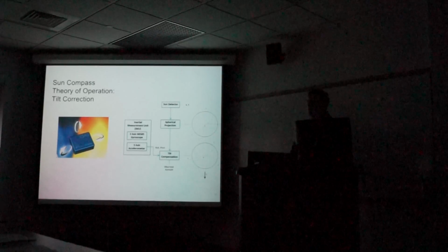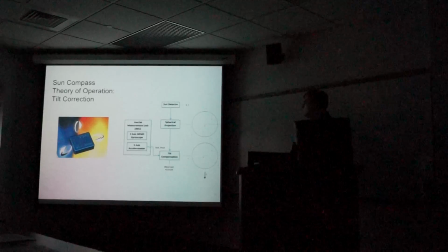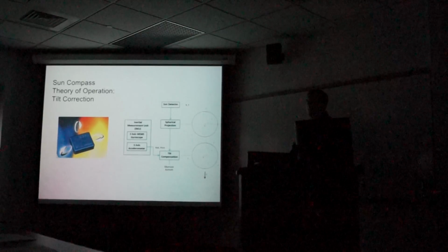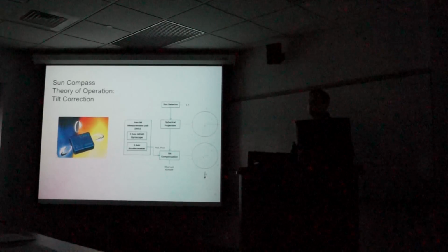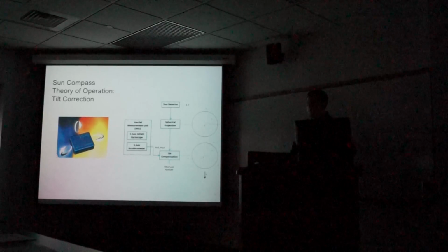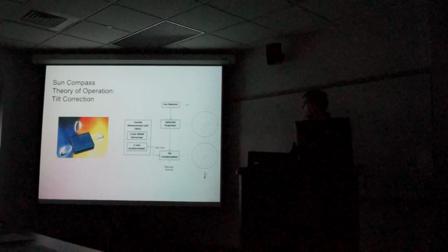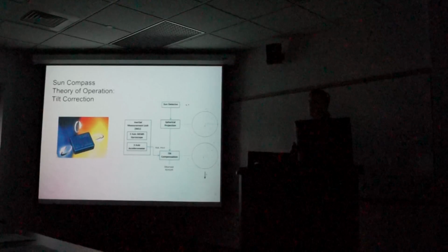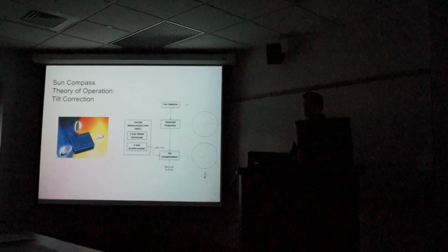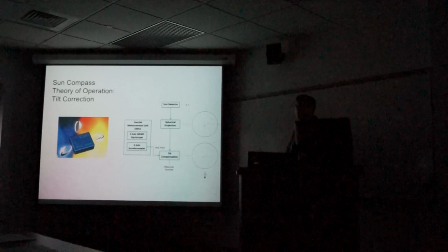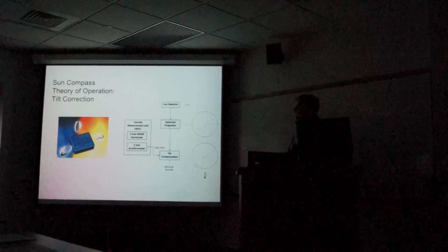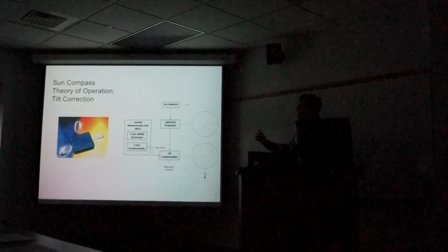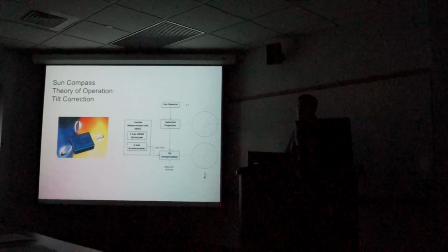Once you have the calibration terms, it's a fourth order polynomial that models the lens distortion. And so it's really convenient because it goes automatically into the spherical coordinates from the pixel coordinates of the image. And then it allows us to use the roll and pitch from the IMU directly. Right, so how did you get the roll, does the IMU spit out roll and pitch? Yeah, well, we fused the gyroscope and the accelerometer data.